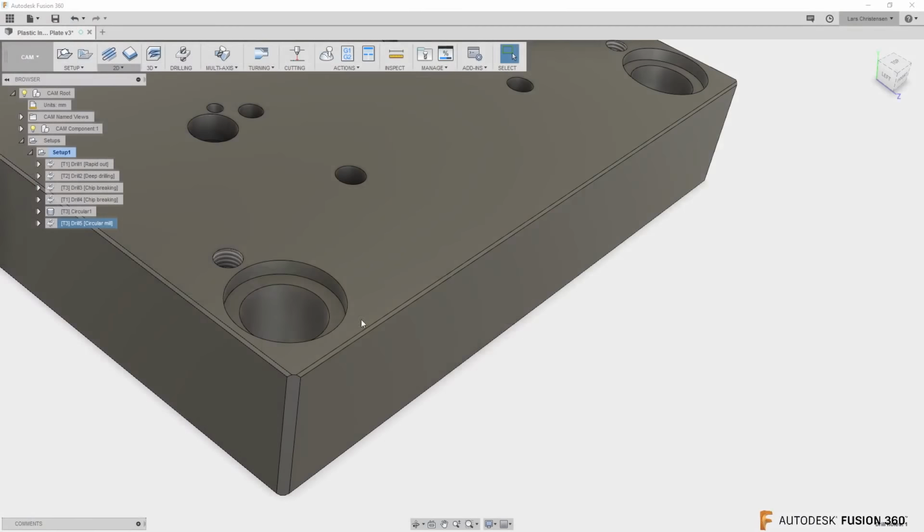Another thing that you can do is relieve your cutter a little bit. So let's say you have a cutter with a 1-inch flute length on it. You put it on a diamond grinder or something, and only take off a very small amount of the cutting edge. If you reduce that down to a smaller amount, you can actually get a better result than that.